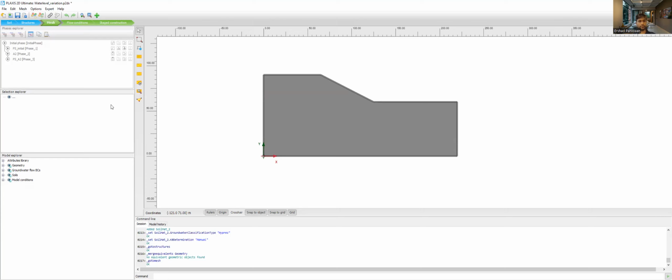So in the mesh option, actually you can create the mesh. Click here, and there is an element distribution option: fine, very fine, coarse or very coarse, and the other options are there. And then when you click this option, view mesh, you can see the generated mesh.